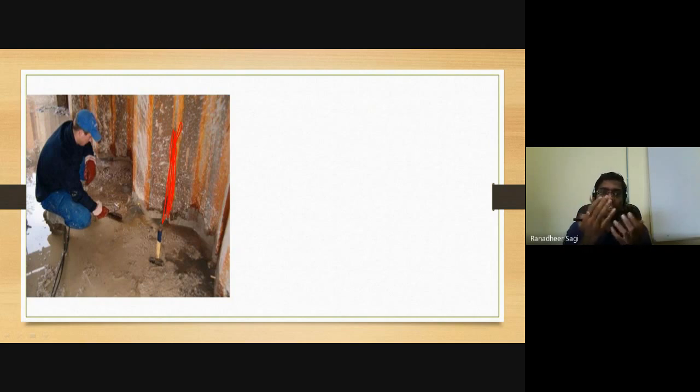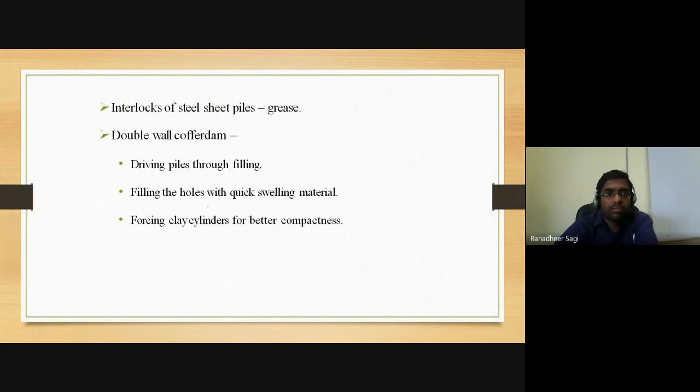Those joints can be properly done by a welding mechanism or by injecting some grout into the available joint space, so that the seepage expected through its cross section can be minimized, or you can address the complete problem by making use of the required grout material there.